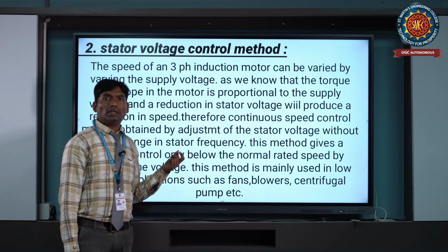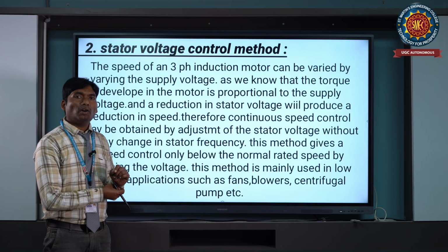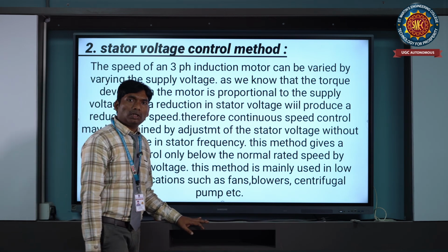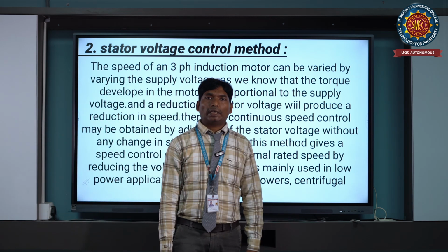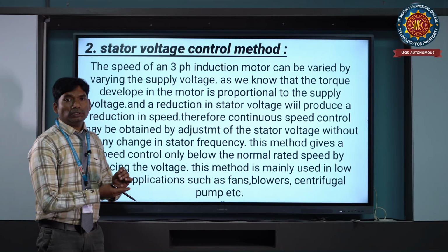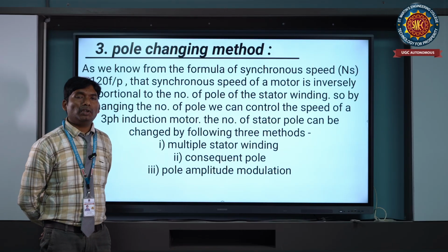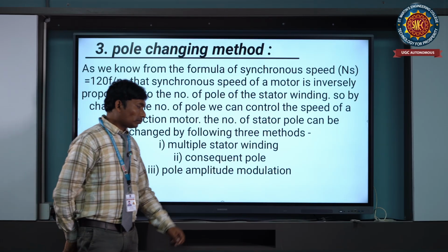Next, from the rotor side we have methods. One is the rotor resistance control method. Second one is the cascade method. The third one is by injecting EMF into the rotor circuit.